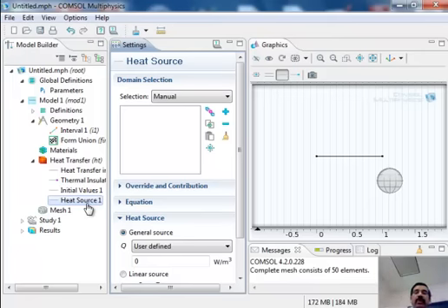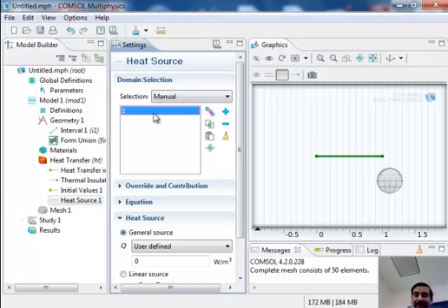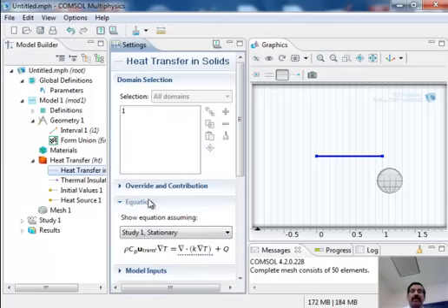Okay. So the heat source is going to be applied in this domain 1. So I add domain 1. In that entire domain, there is a heat source Q term, and the Q term is defined as minus M times T. M is what I have calculated in the parameter space, and T is my unknown variable. How do I know T is the symbol used for that variable? In this equation, that is what is appearing here, T. So T is my unknown, and Q is what I have just now defined in the heat source term. Here is Q.